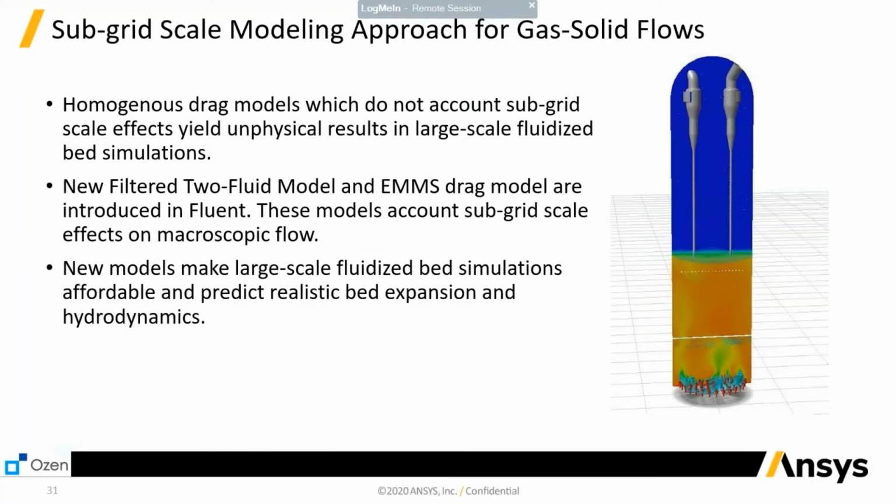The other method which has been added is the subgrid scale modeling approach, specifically for gas-solid flows. The method we had was the homogeneous drag model, which had some challenges. It wasn't holding up that well against some test data.